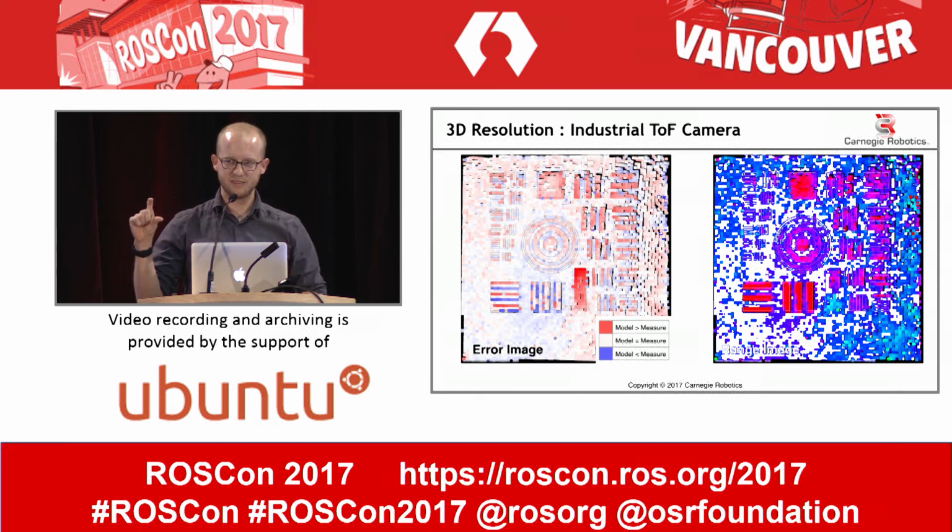The top half is visible, and then the bottom half of that ramp is completely gone, and you see that reflected in the big red stripe in the model versus measure error image. We believe this is happening because that slant is actually reflecting IR energy away from the camera back down to the floor, so we're not getting a good return off that wedge, but we get a much better return off the things that are parallel to the camera.